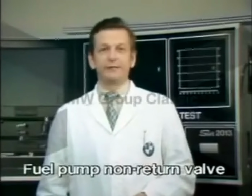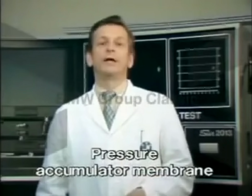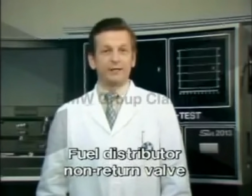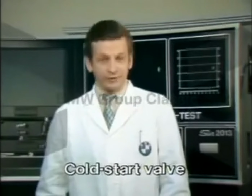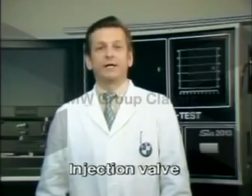Should this not be the case, then the non-return valve of the fuel pump, the pressure accumulator membrane, the non-return valve in the fuel distributor, the cold start, and the injection valves must all be checked for seal.